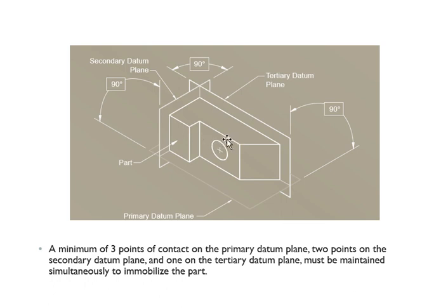Of course, outside of you, the physical thing is only this one. That's what we call a datum. It's a simulated plane, because it is a datum simulator, because you're simulating it virtually inside your head, imagining, oh, if that was there. Of course, if you want to see the physical thing outside, you're going to have to bring in another object. So that's what the first three slides are telling you: to bring a gauge and stick it right here on the bottom surface, and in between them, when they are in contact, you get that plane. That's what it said.